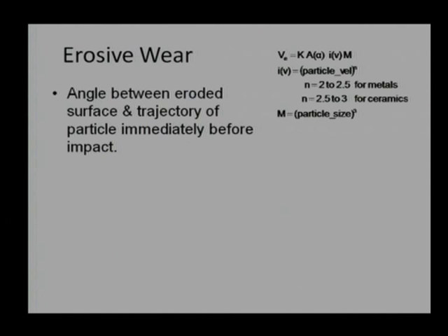Now, first let us define impact angle in an absolute manner. It is not necessarily about the particle coming from 10 meters away and the angle of inclination then, but just before impacting, what is the velocity and the angle of impingement just before impacting the solid surface, that will affect the result.